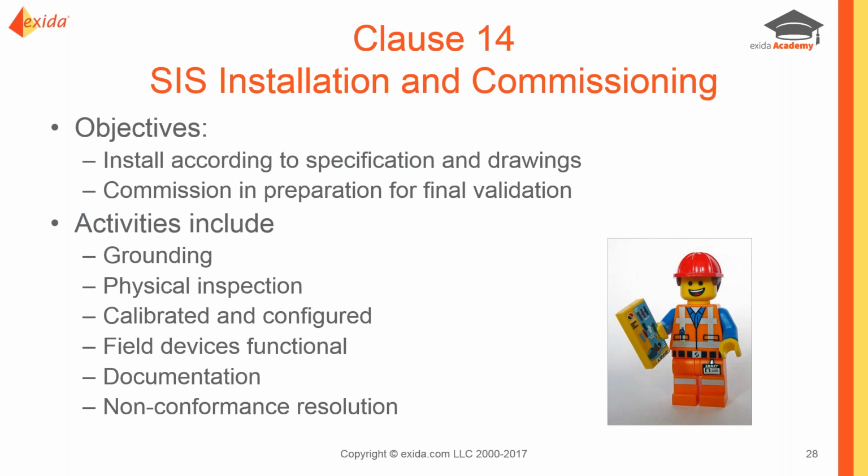And how do we resolve any non-conformances that are found? This is a transition period where we're getting ready for handover, and obviously the owner acceptance team is not going to want to accept the process until they're very comfortable that this has been met. These activities need to be tightly coordinated within the project schedule to assure that they all get done in the right way. And in most cases, this is going to be your first application of the full proof test, making sure that it's feasible in the long run and that it's going to provide a proof test to do all of the appropriate testing, and it might be the first partial valve stroke test.